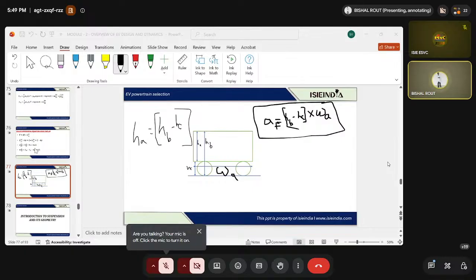Yeah. So you can see there is a 1D lookup table, 2D lookup table. You can plot this 1D lookup table over here. Right now I'm cancelling it, right? If you click this 1D lookup table from here, you can create a value over here. You can see a point over it, edit table and breakpoints. You will click over here. Once you click on edit table and breakpoints, you will get one thing, right? Now you have to change the value.